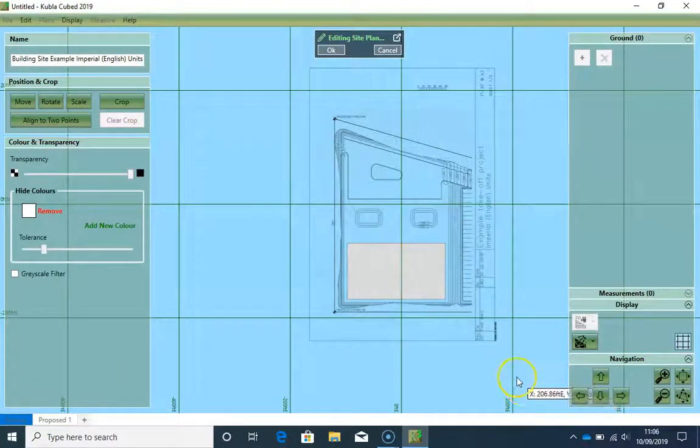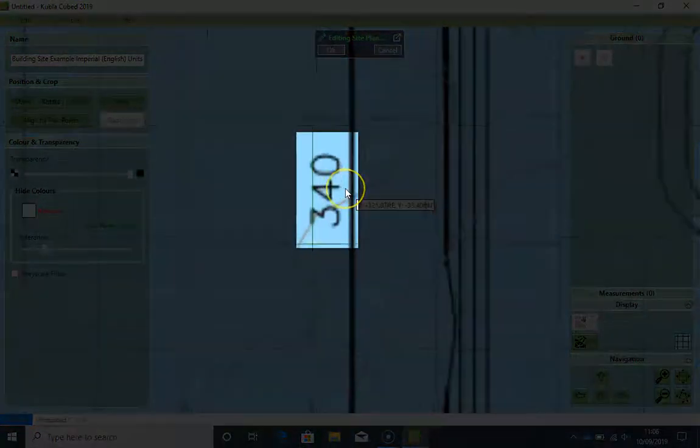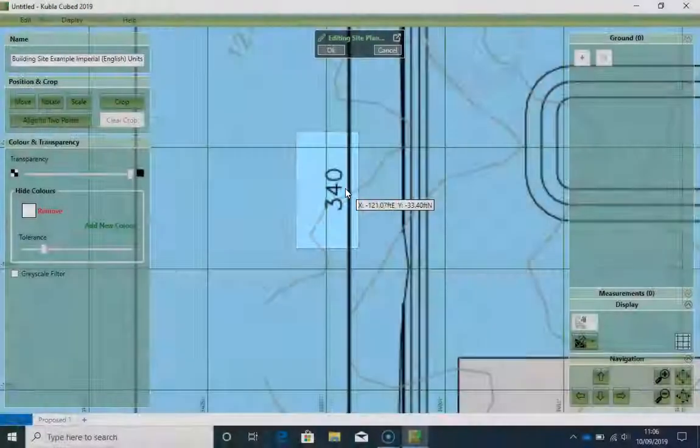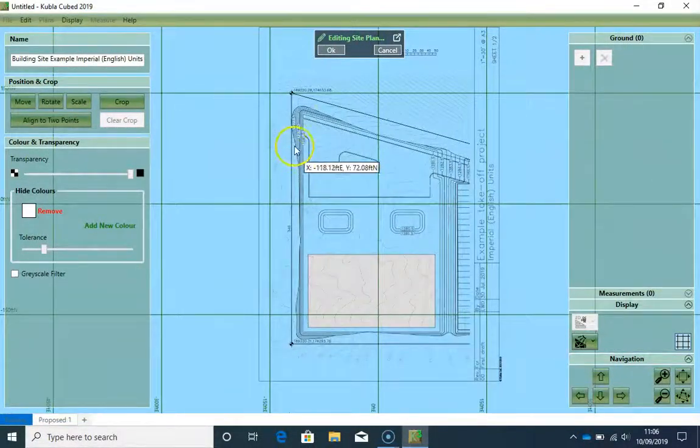Now obviously if the scale is wrong, then all volumes will be wrong. Therefore, never forget to check whether you have scaled correctly to see whether the software provides you the same value as the drawing. For example, here we can check the length of this marked length, whether the software will give us the same value, 340 feet.